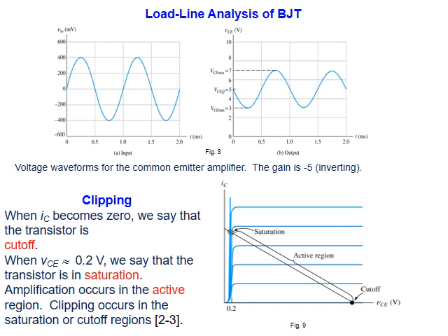It's worth mentioning that if I compare the input and output signal, the small signal with the large signal, you see here, this is in millivolt, this is in volt. This is Vn, the V base emitter, the input, small value, and this is VCE, the large value. First of all, here, let me say 400 milli, it means 0.4.